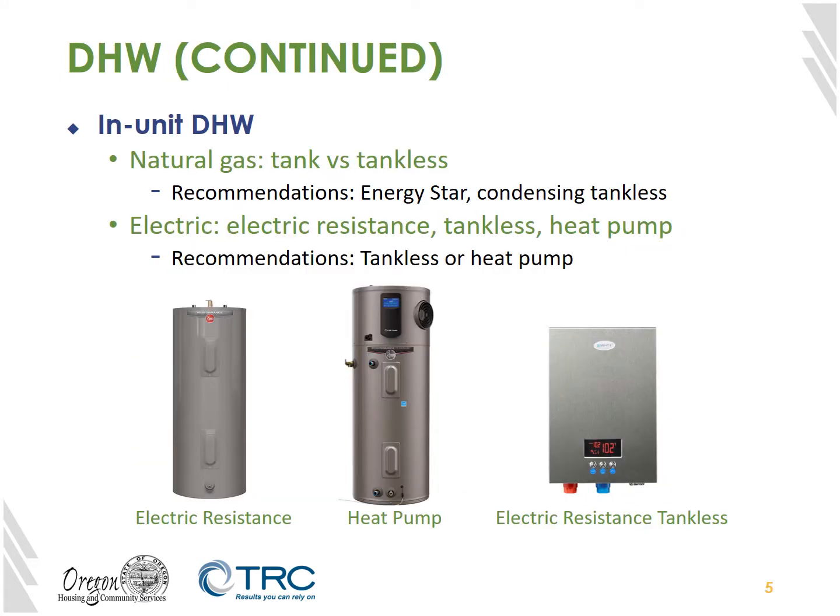The majority of the systems here are in-unit electric systems. Standard tank-type electric resistance water heaters can be replaced with heat pump water heaters or tankless water heaters. Heat pump water heaters use heat from the air to heat the water and are 3 to 4 times as efficient as electric resistance. However, because the heat pump system is situated on top of the tank, they require somewhat more space, and they require airflow. This airflow may be achieved with a louvered door directly drawing the cooled air out of the space.